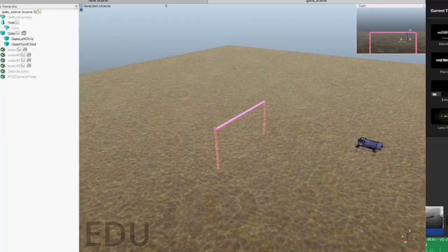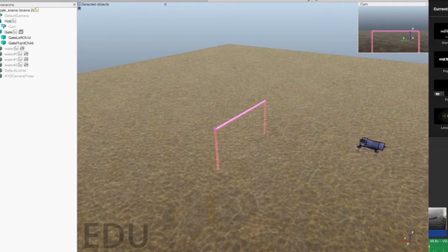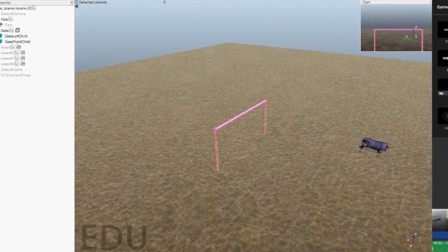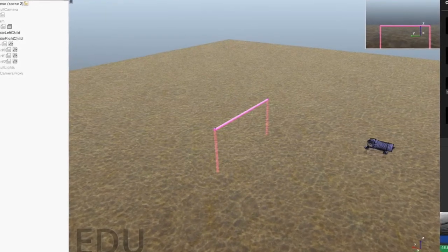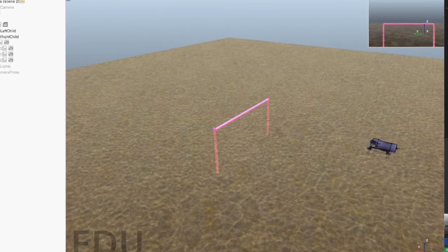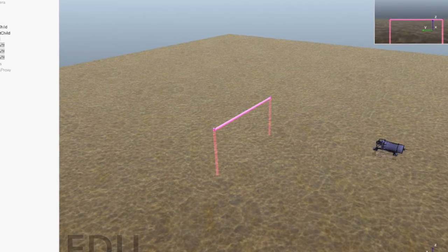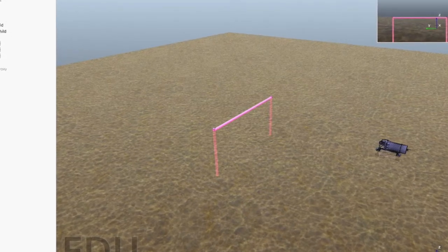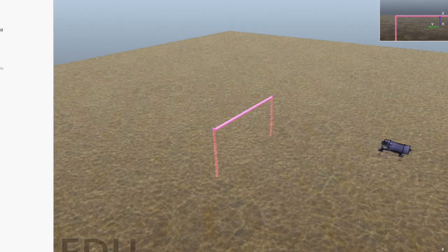Given the online nature of the school year, most of the propulsion testing was done in a custom virtual environment that we put together. The virtual environment simulates a multitude of physical factors, such as buoyancy and water currents. We created a URDF model of our new frame design, and we formulated models of the various tasks, like the gate, for example. The visual part runs in a program called CoppeliaSim, but all of the background math runs in Python, making our simulation very flexible.